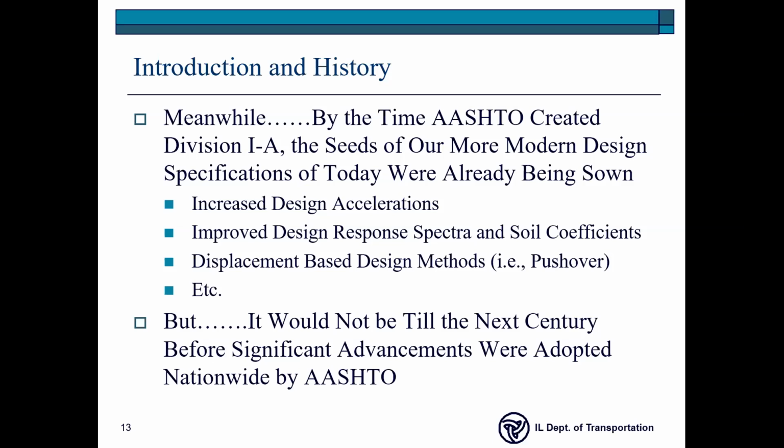And the original soil coefficients for this, they really weren't very good, and so they were working on more sophisticated methods to figure out how much amplification there was based upon the type of soil that you had. And then there was a whole new type of design method also being developed called displacement-based design, which a lot of people call pushover. The older style design method was called R-factor design, okay? And the easy way to term that is force-based.